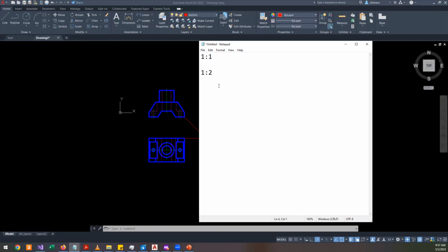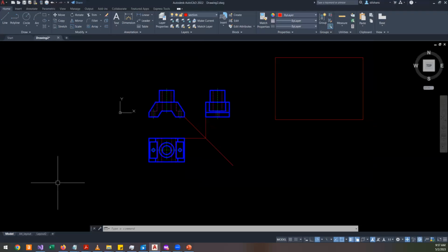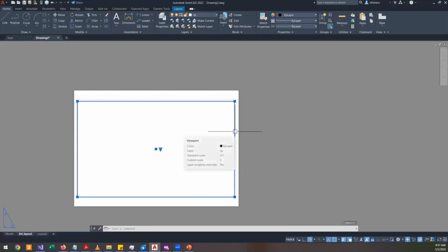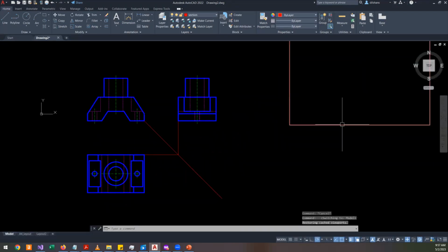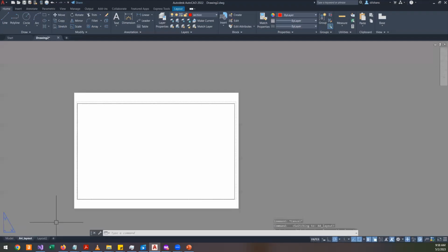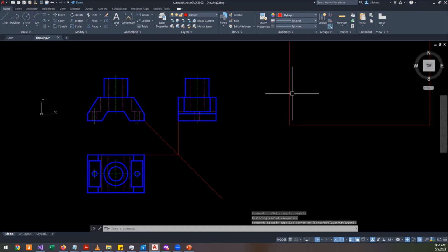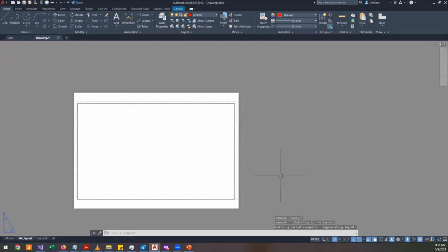Actually, there is a different method where you add the dimensions onto what you call the layout. That is also used especially in mechanical engineering drawings, where you model a 3D part and then generate the 2D drawing. However, with my experience in the industry, in civil engineering drawings, very big mechanical engineering drawings, especially structural drawings, they don't insert the dimensions onto the layout. They put everything onto the model space, and from there you generate the layout. I will discuss the layouts next week probably.